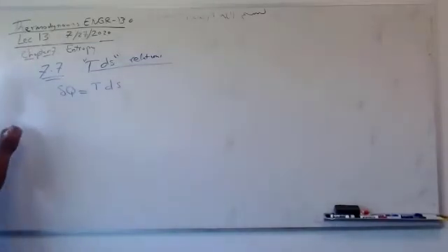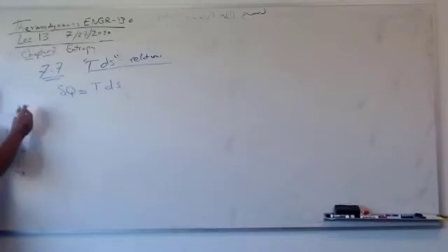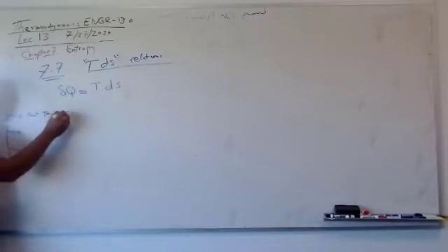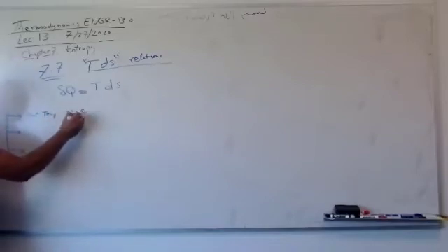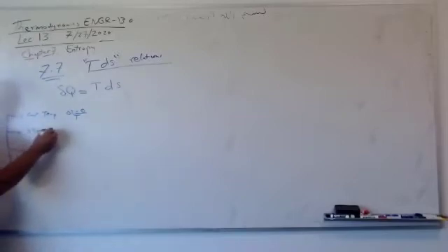We're going to get here. So we have kind of 4 cases. Remember this, guys. The first case, we have T delta S. We use it, for example, for constant temperature: just delta S equal Q over T. The second one, we can use for the steam table.